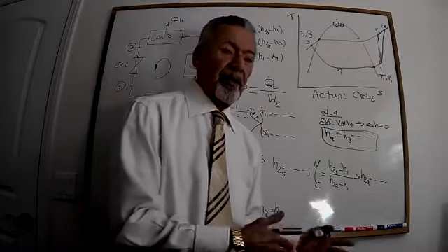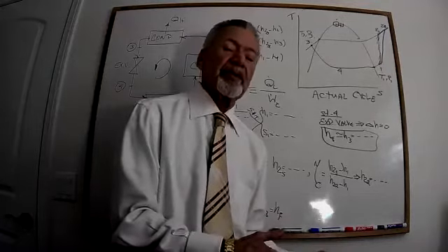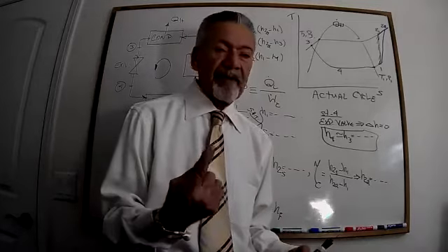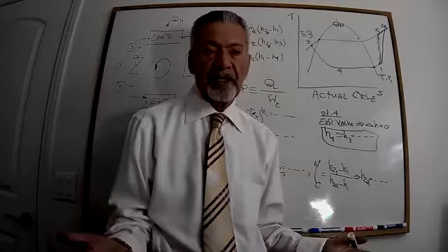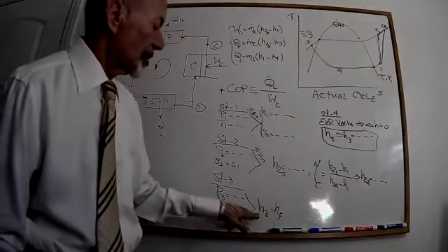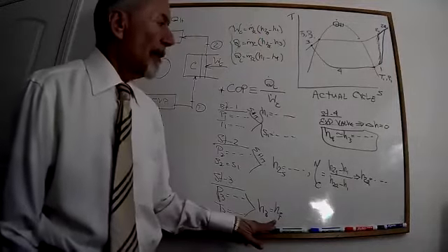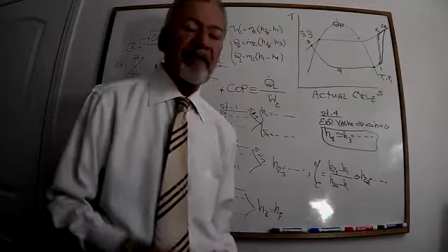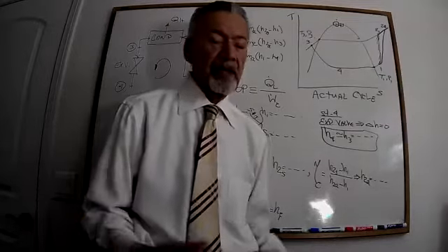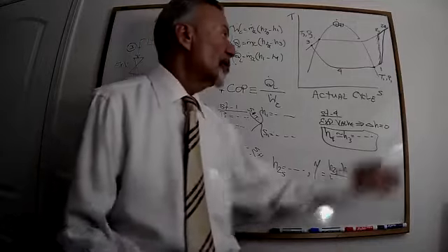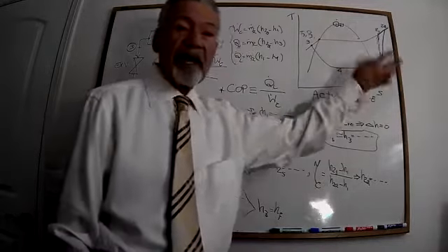So whether you're located in the compressed liquid or saturated liquid, we have only one table for it, and that's a saturated liquid table. Since you are on the liquid side, you use H of F. If you're on a superheated, the superheated table doesn't have H of F or H of G or any of those. You just have H, that's it. So you just find out the H value and S value.